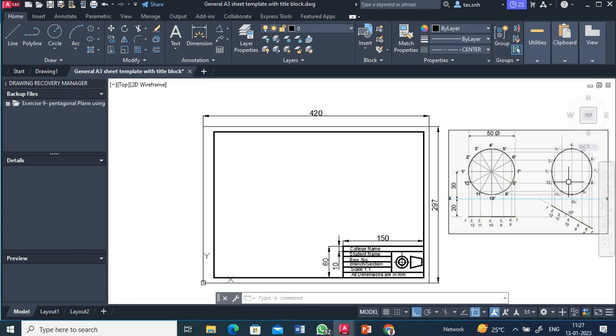Right. Now I am going to draw this diagram here. So I need an XY line first. That blue colored line is the XY line. So for that I have to choose this normal line with the bilayer. We can select it and then go for line. We can switch on ortho mode, and we can draw a true horizontal line.